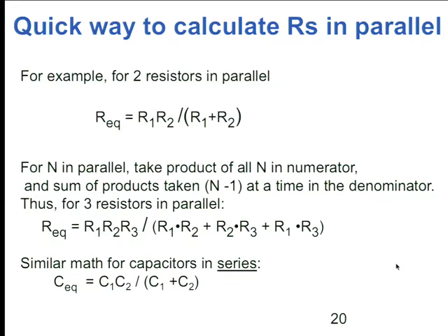This is about 3,000. There should be 10 times more voltage across here than here because this is 10 times more resistance. And this one is a tenth as much. So let's just see if that's true. I haven't done this before, but I believe in Mr. Ohm. So, almost 12. And we're saying it should be 10 times less because this is 300 and this is 3,000. So I get almost 12, and I say a tenth. Should be about 1 volt across here. And it should be the same across both. There you go, 1 volt. And the same 1 volt across here. And the same 1 volt across here because this is all connected by wires. Okay? See how we do that?